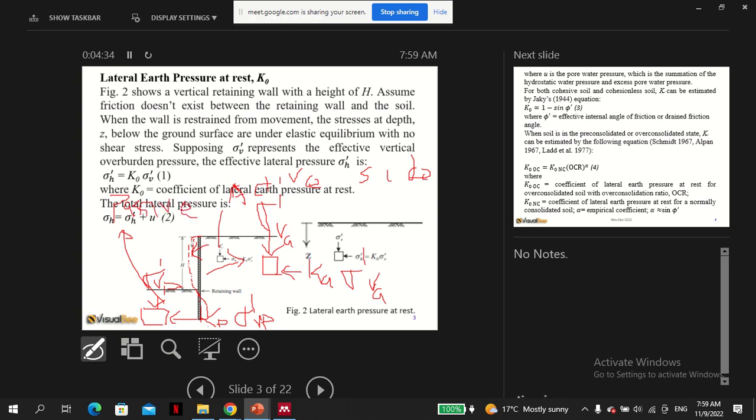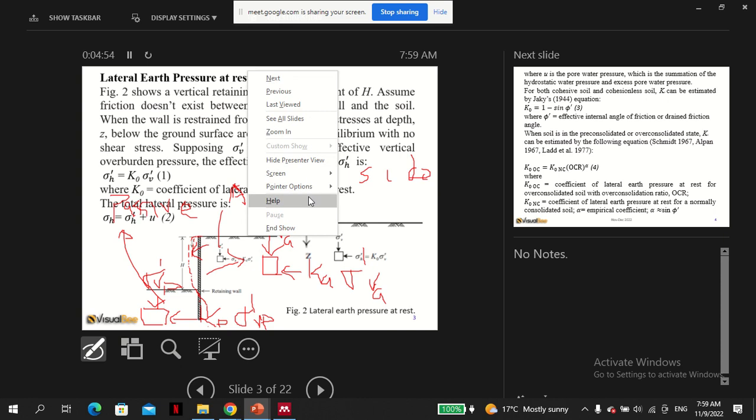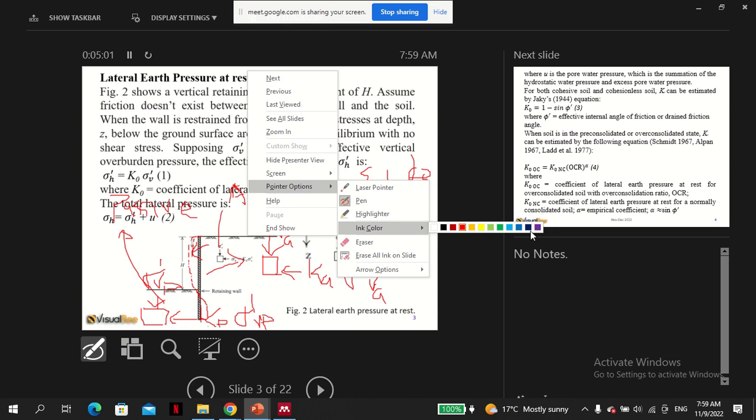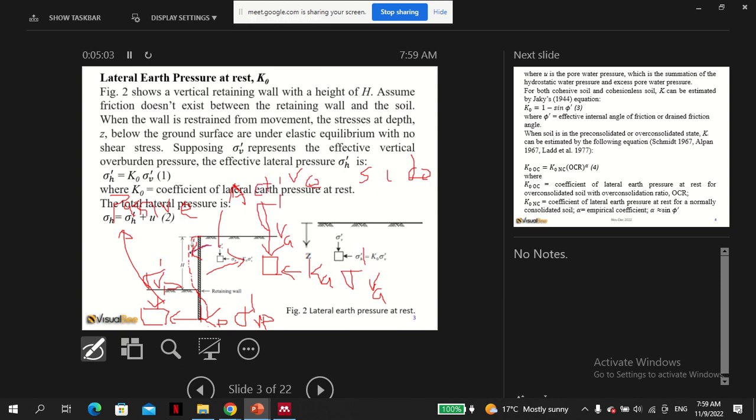So you've seen the way we calculate the K naught for at rest, when the excavation has no influence on the stress state. But now when there is imbalance, one is the active side, another one is the passive side. The reason is that on the active side, the soil is tending to move away, pushing the retaining wall away.